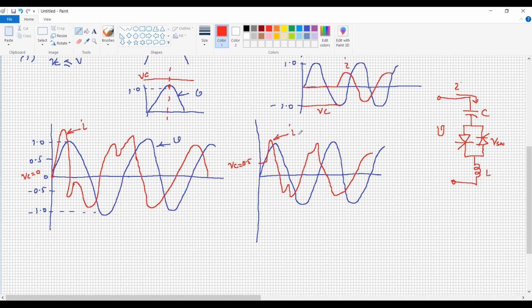So we can say that if the capacitor voltage is equal to the system voltage, there is transient free switching. If the capacitor voltage is greater than the system voltage, the right position to switch on the capacitor is at the maximum crossing, where dV/dt, the rate of change of voltage, is smaller, and it will give transient free switching of the capacitor.